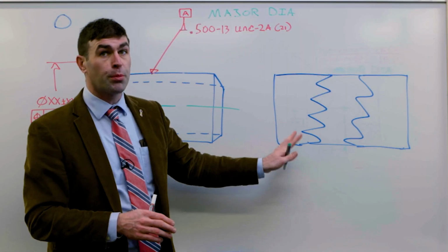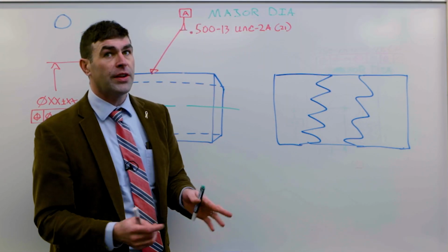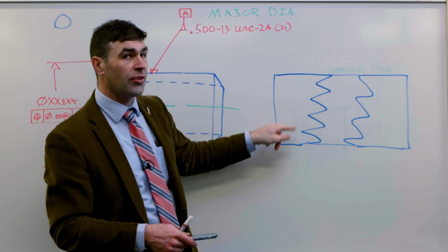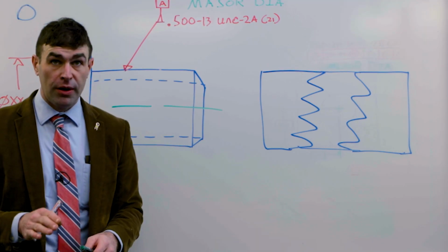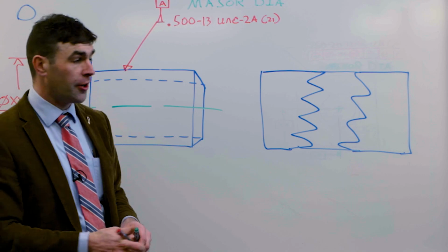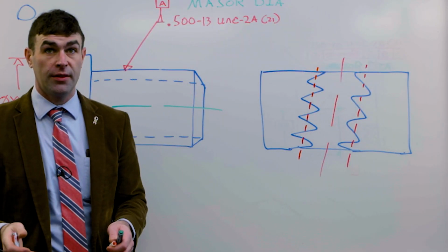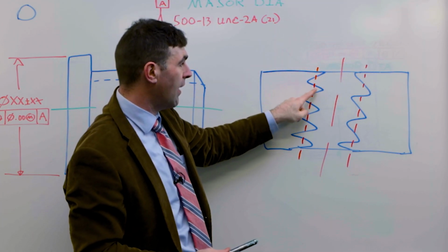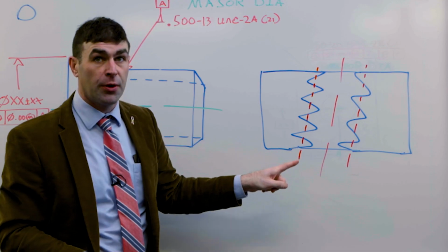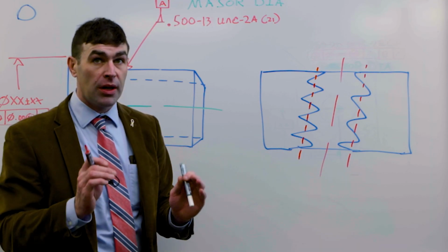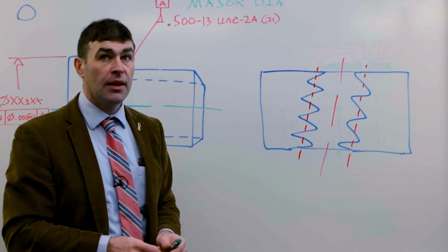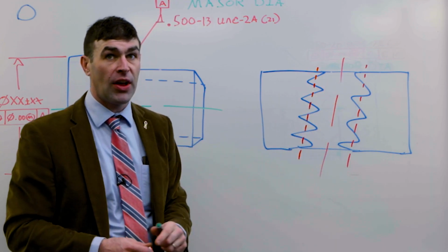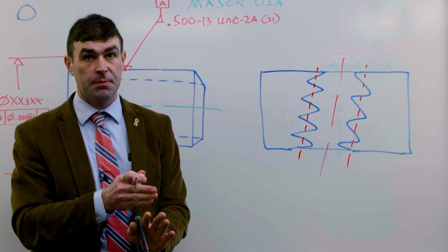Okay, so I know this isn't the prettiest screw thread, but what I want to get across here is it's clearly oriented wrong. We would want it to be perpendicular to this top or bottom surface. Now, if we found the axis of the pitch cylinder, it would look something like this. If we took a threaded gauge in here, it would follow the actual pitch cylinder of the thread. Now, if we took a gauge pin and did the same thing, the gauge pin would be sitting inside of the minor diameter and the axes would be coincident.